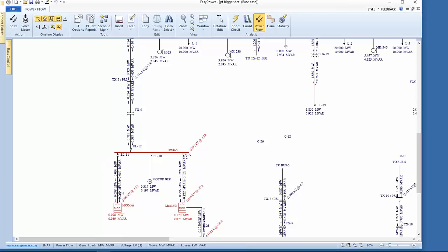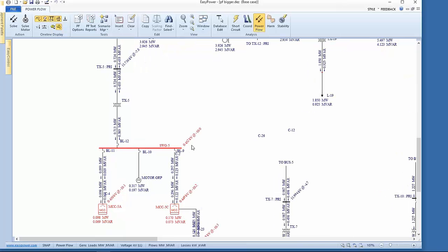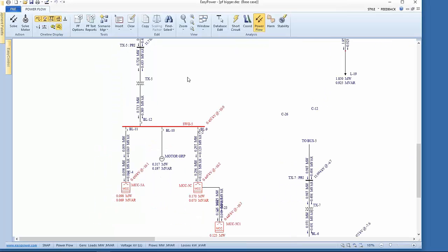This is a 480 volt bus. It looks like we're down to 450. I may have 2 choices. There's a couple choices, but I don't really want to get into the design elements of this, but certainly the tool allows us to do a what-if situation.